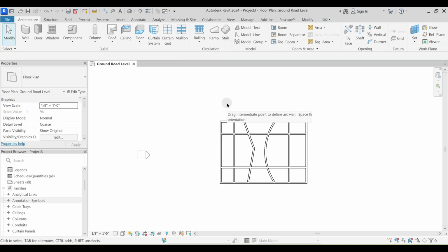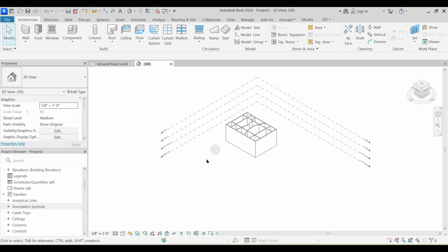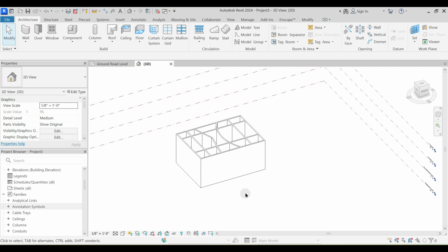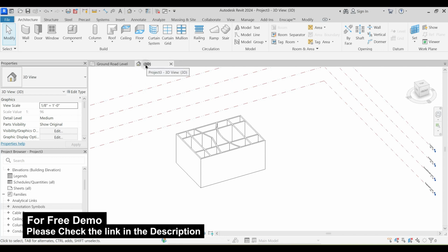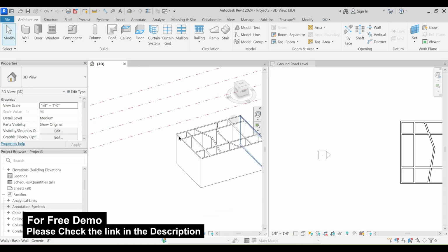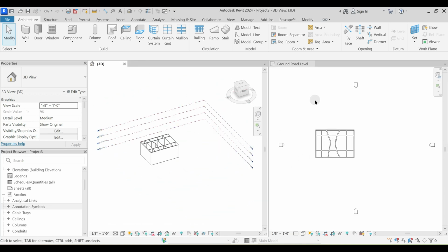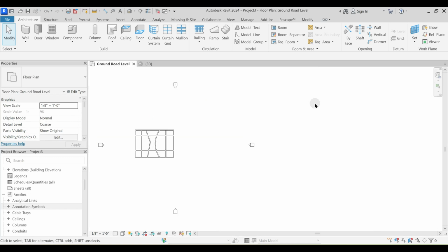Yes, okay. So I have created a few walls, and if I go to this particular 3D view, I forgot to tell you that Revit is a multi-dimensional software. Whatever you create in 2D automatically gets converted into 3D. Now, one more command for today. Let's say you want to see both of these views side by side. Then what are the options? The option is WT. This is called the tile view. And again, when you want to see the extended view of any one view, it is the opposite of side by side, TW.